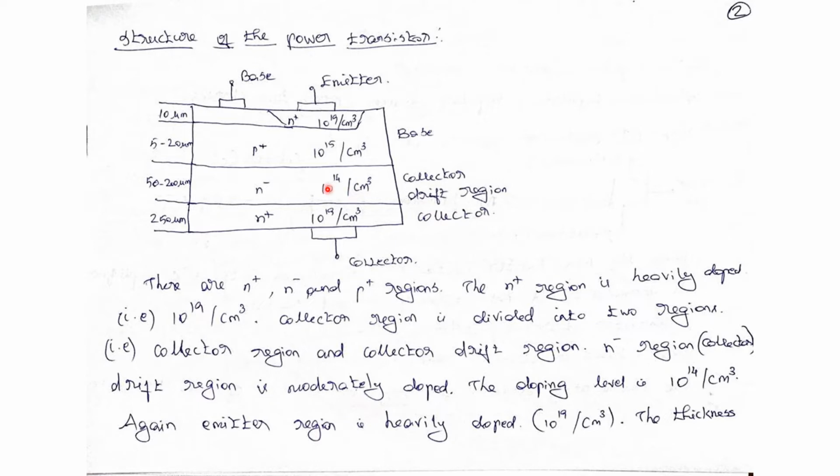Then after that, I already explained in the diode what will happen in the drift region, because holes are injected into the drift region from the P plus area. Then electrons are introduced into the drift region from the N plus region. Here the electrons and holes make a pair. Some free electrons are also there. They will get kinetic energy, so they knock off other atoms to release electrons. That is what is happening in the drift region.